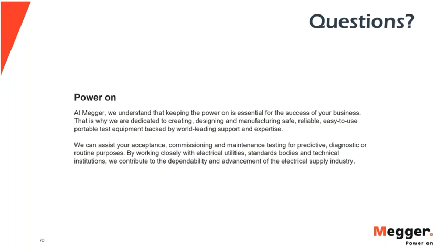Is the individual temperature correction for the unit under test or for the test instrument? Okay, so the straightforward answer is that it is for the unit under test. And the whole reason behind this is, like Diego said, we know that power factor varies depending on the temperature. If I have in hand a power factor result from 3 years ago, and the unit was tested at 18 degrees C top oil temperature, and I'm out there